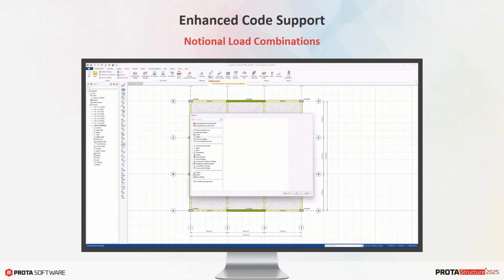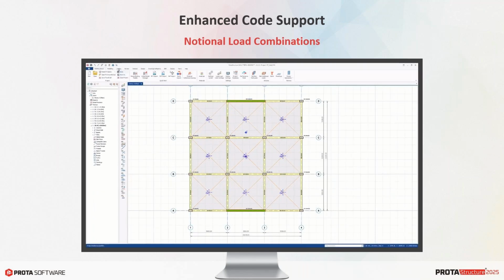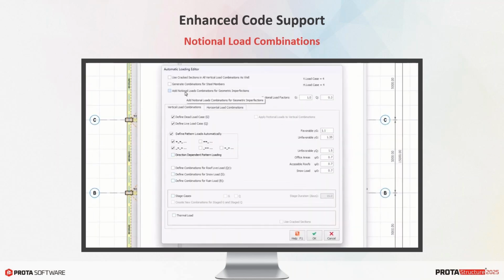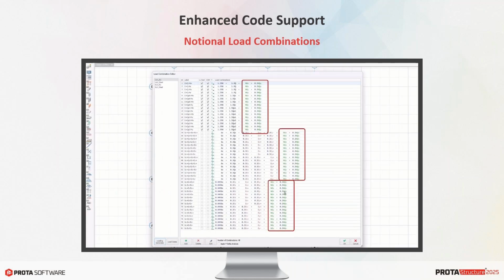And besides, the dead and live load fractions that are used to calculate the magnitude also need to be customizable. All of these requirements are now met in ProtaStructure. You can now flexibly apply notional loads to any combination type with any load case coefficient. You can also interrogate the load case results in the analysis post-processor, as usual, of course.